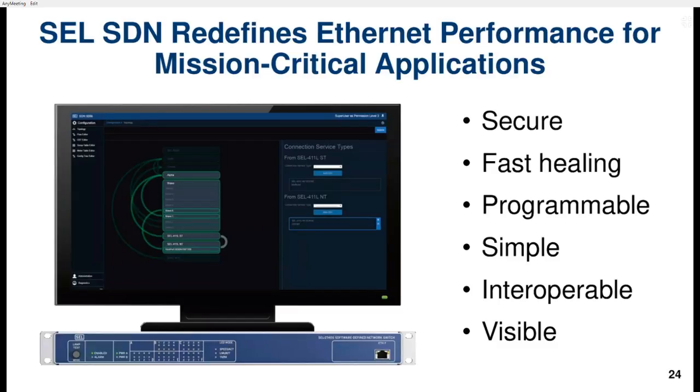The end results of the CEDS, Watchdog, and SDN project was a system that was denied by default, ultra-fast healing, programmable system that still interoperated with traditional Ethernet. And the part that I am really excited about was the security is the visibility of OpenFlow and SDN offer the user who creates granular flow rules. More on this in a little bit, but I want to describe the difference between traditional SDN and OT SDN.